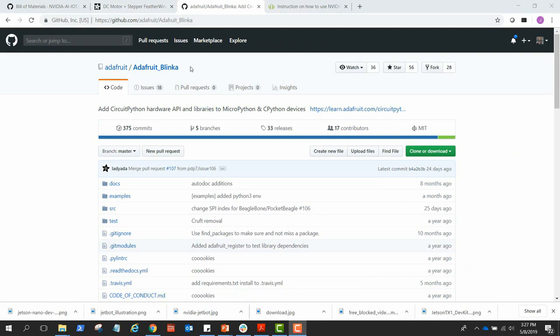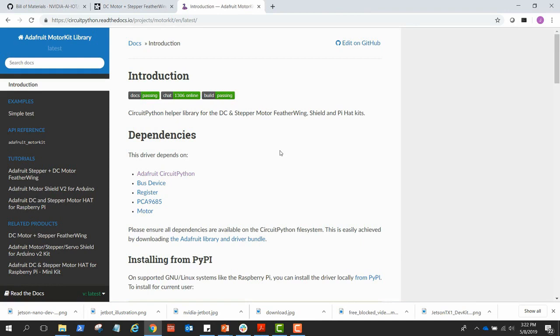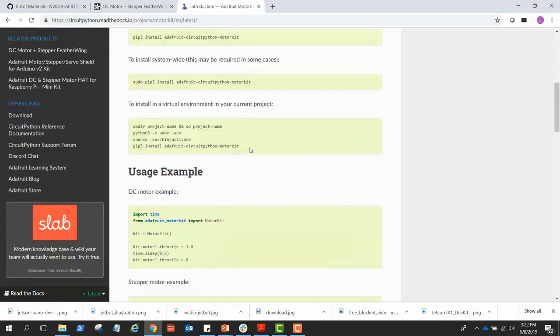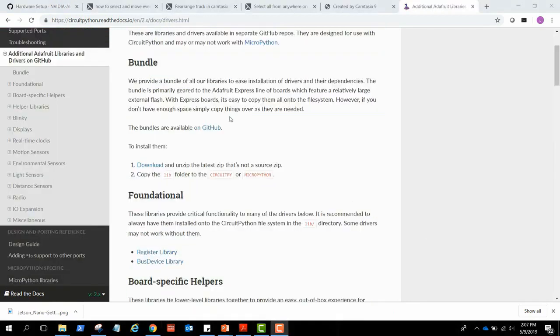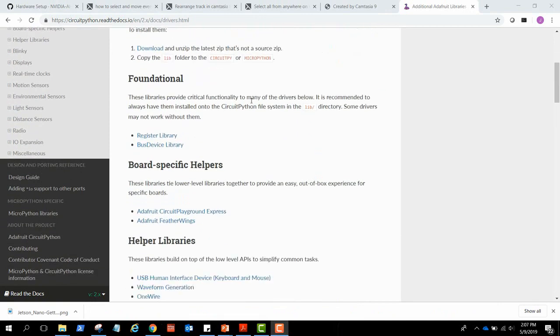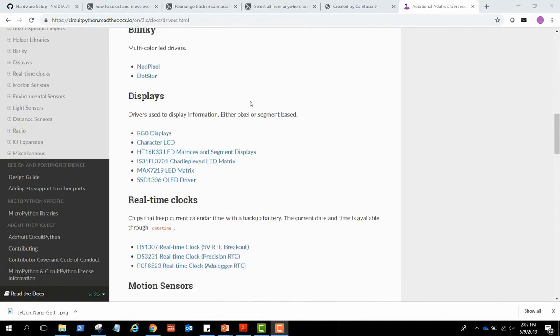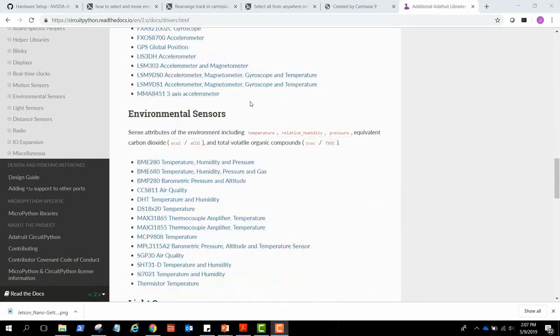It was especially easy to control these motors with software given the new NVIDIA Jetson support for the I2C and GPIO portions of the Adafruit Blinka library. This support allows us to use Python libraries like the Adafruit MotorKit library, which makes it very easy to control motors. This also allows us to use various other sensors that are supported by Adafruit Blinka I2C and GPIO.